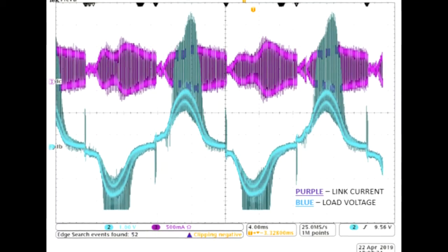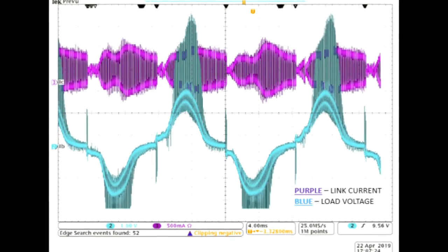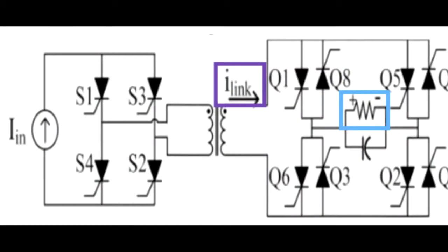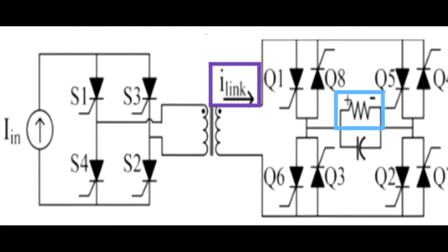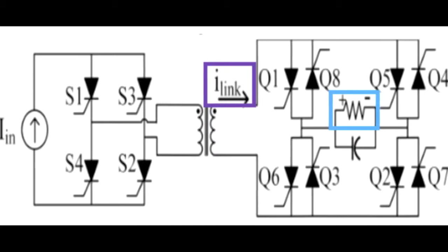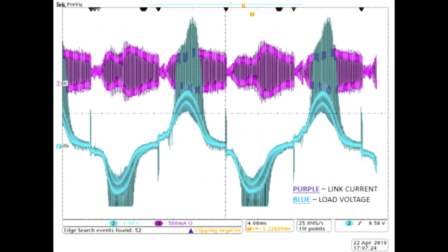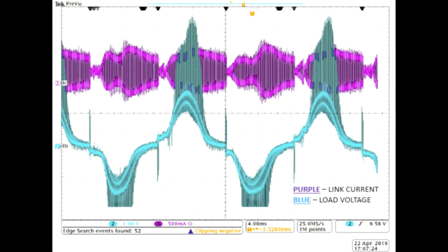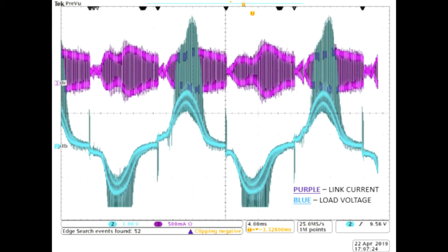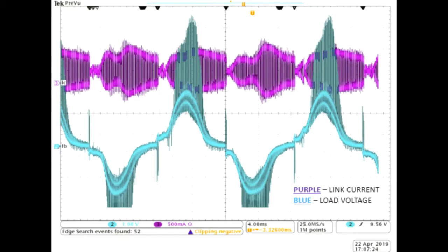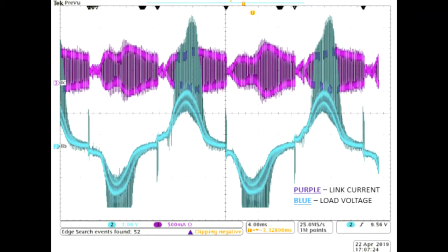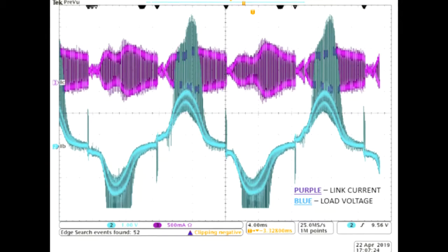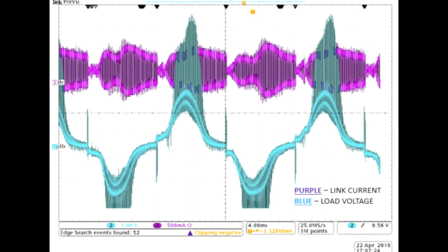The changes that were made include the following: changing the primary frequency from 1 kHz to 10 kHz, increasing the capacitance to 116 microfarads, increasing the resistance from 20 ohms to 1 kiloohm, along with decreasing the input current from 1 amp to 700 microamps. While there is still some noise at the peak voltages on the sine wave, we can clearly see the sine wave, which was the goal of our project. This gives researchers a solid foothold to continue researching this technology in the future.